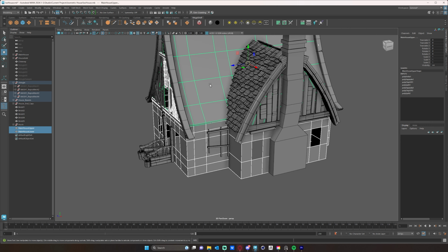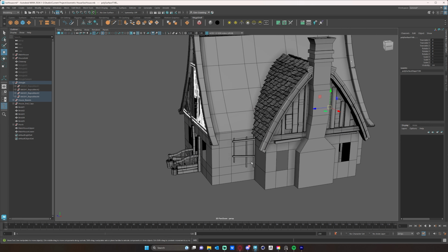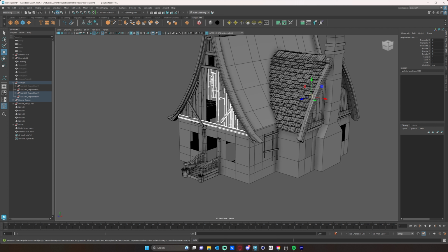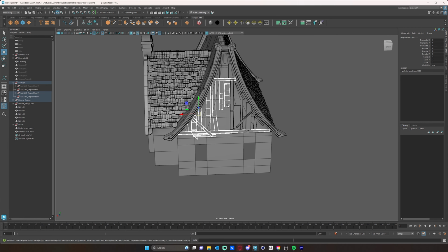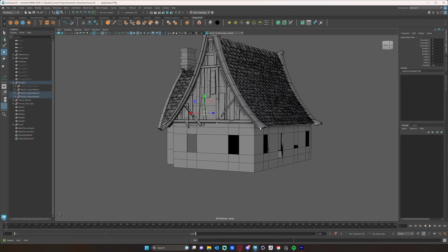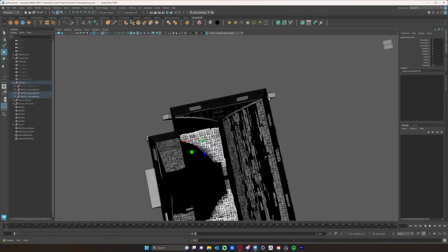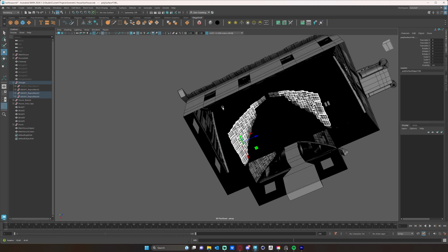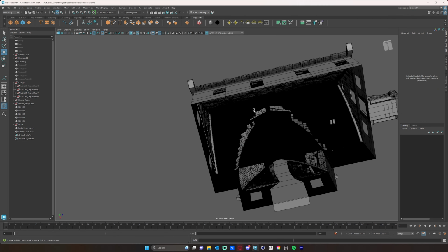But now what I can do is just deselect the things that I don't want to delete. It can be a little tedious. I believe there's a hotkey also where you can Control Shift to deselect some of these things. So then we can just look, make sure that we only have the shingles we want to get rid of selected, and then I can just delete those.